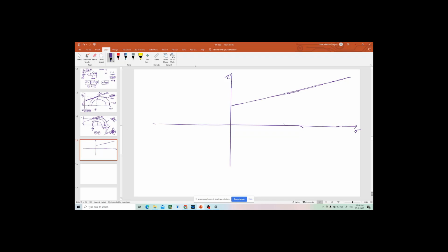Here this is cohesion C and this is friction angle phi. Now take any soil element; let us say that soil element has failed because of the application of sigma 1 and sigma 3 on the major and minor principal planes, and other planes are as they are.